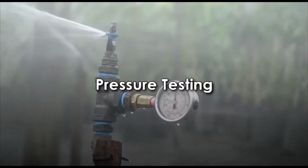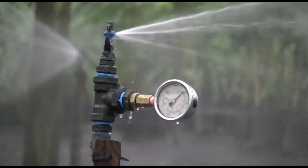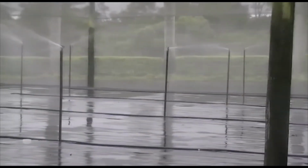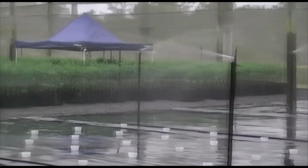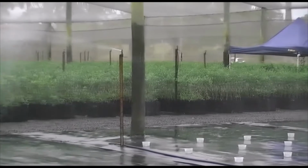First, it is necessary to locate a pressure gauge or measuring point in the system to record the pressure at the irrigation zone or grid during the evaluation. Pressure measurements at the pump or the pump house do not always reflect the pressure available at the test area, but can be useful for comparison or future troubleshooting.